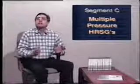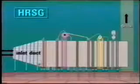Okay, so let's take a look at the internals of this HRSG. First, look at the LP section. In this unit, we have a condensate preheater, which heats condensate on its way to the de-aerator. On this particular HRSG, the de-aerator is of the integral type. It is built into the HRSG.